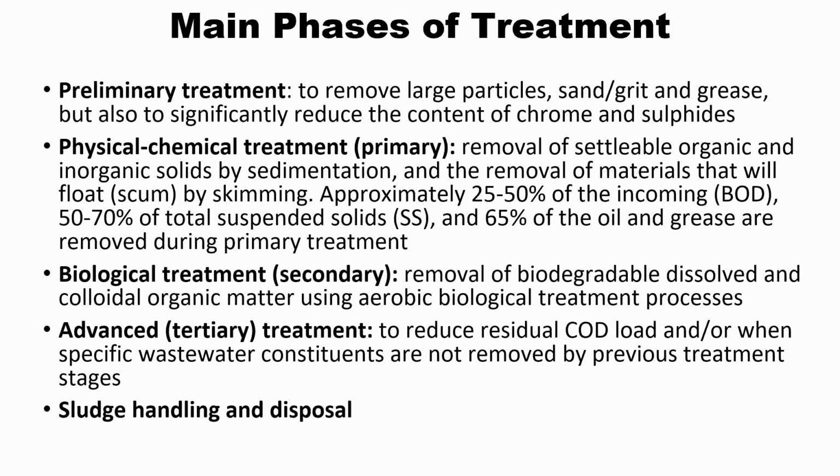And talking about the biological treatment, it is the removal of biodegradable solids, dissolved and colloidal organic matter using aerobic biological treatment processes, and advanced lagoon methods are also used. And advanced tertiary treatment also includes reducing the residual COD load, or is used when specific wastewater constituents are not removed by previous treatment stages.